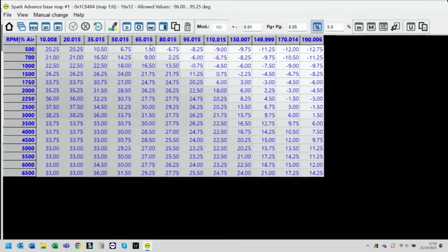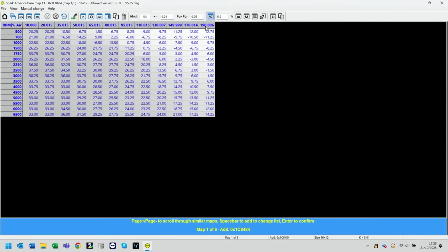Yes, if we start to look towards our stage 2, we can push further on the boost. As we mentioned early on in our investigation phase, there are values that do support a higher level of tune on here. However, the important thing to look at, to go back to our spark advance, is that as soon as you go beyond 190% of air in this engine, you're off the end of the map. Now, in our diesel webinar last month, you'll have noticed we had all the capacity we needed within the standard axes. Yes. So we could max the car out on stage 1, even stage 2, with those standard axes. So what would the strategy be here?